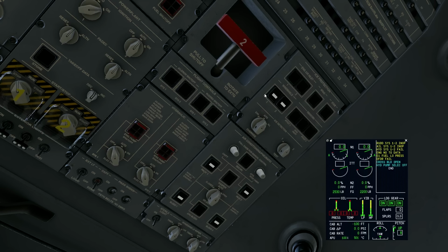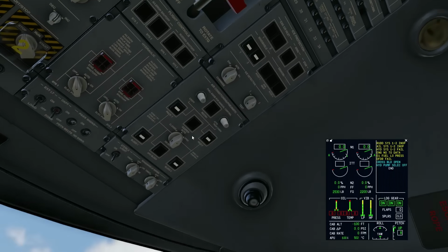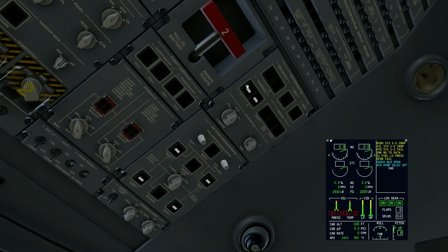The windshields are simple. They do not have any sort of scheme to them. They are simply on-off. So we turn them off at the gate unless we really need them, for 2 reasons. One of them is you actually hear them in your headset. It makes a kind of crackling noise, interference. The second is just to avoid overusing them, especially at the gate. I don't particularly care unless the windshield's fogging up or we're really picking up snow and ice and I want to melt them and the wipers aren't getting them. You can turn them on.